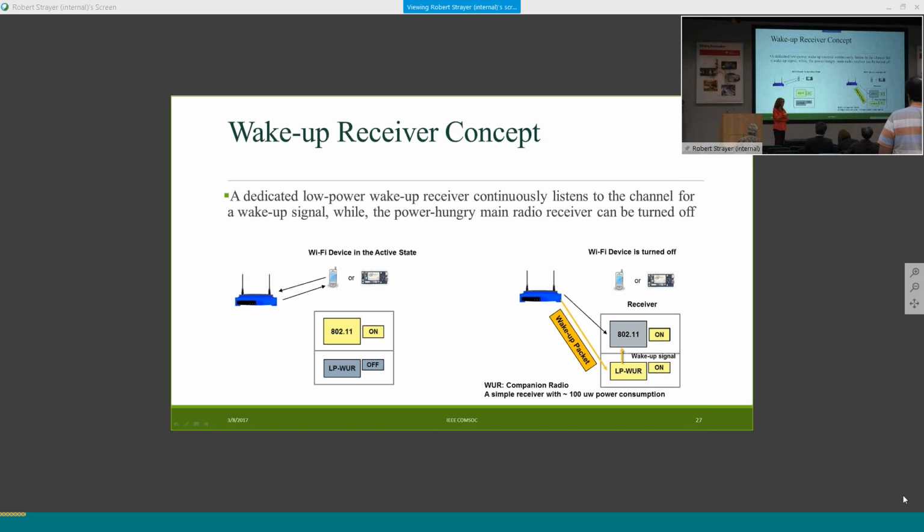Yeah, that's a very good point that you don't want to wake up everybody, right? Because once this packet is received, it sends on the main radio. Another concern that people need to carefully address is security. Let's say a hacker wants to come and drain all the batteries; all it needs is to transmit the broadcast wake-up packet and wake up everyone. So security needs to be addressed.